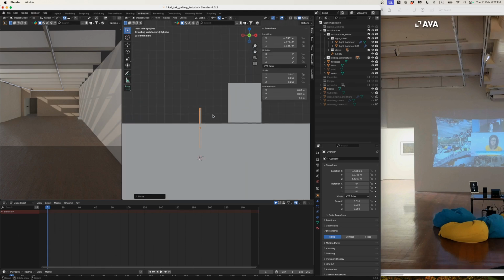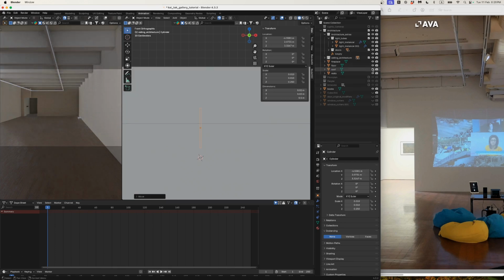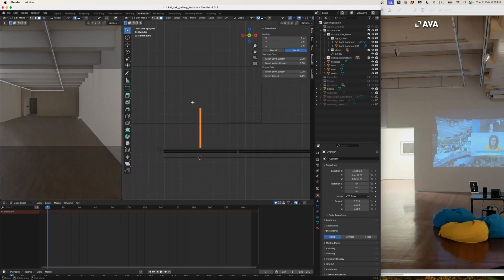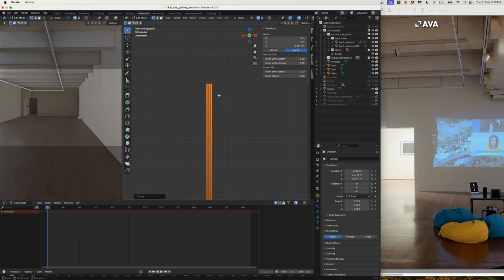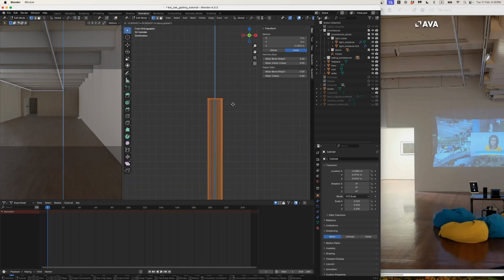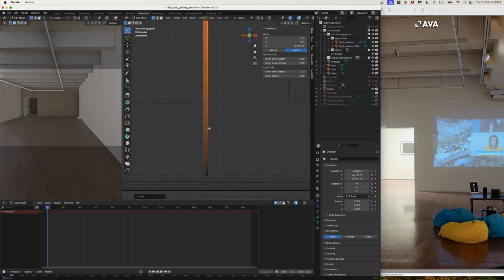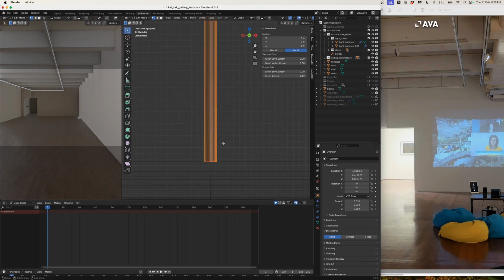I think it needs to go up a little bit higher. In this case, I'll just reveal my roof, go into wireframe, press tab, grab all these vertexes, and I'll just snap them GZ up to the top. And then, because I like these little gaps, I'm just going to drop it down a tiny bit and do the same here. I might just lift this up just the tiniest bit.